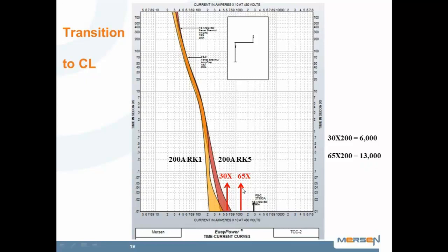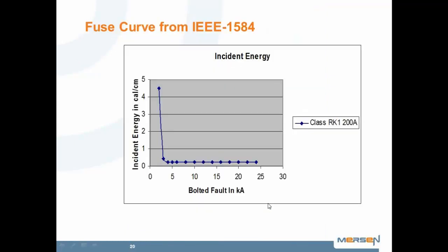So you can see the requirements are quite liberal for RK5 fuses and more strict on RK1, similarly for Class J. So from the right, it's current limitation. To the left was no intentional time delay, and way to the left was time delay. So those are the three sections.